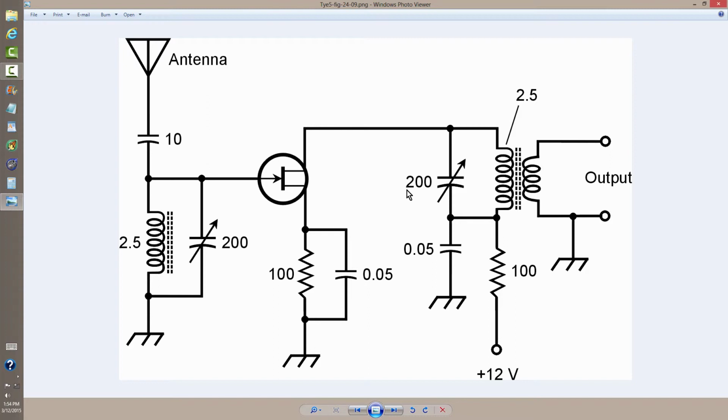When it's not tuned to resonance, in effect the impedance is very low, and this is shorted for radio frequency signals to ground, and you get only a minimal amount of gain or even a loss. So that's why you see a resonant peak here, even though it appears, if you connect the probe here or here, that the signal coming in and the signal coming out are both at the same circuit point. How does that work? I mean, how can that be, you might ask? Well, that's how. The signal itself is shorted out to ground most of the time, except when this circuit or this one, or preferably both of them for optimal circuit operation, are tuned to resonance, so that these impedances become very high, and it's like opening up a switch and letting the signal on through instead of shorting it to ground.